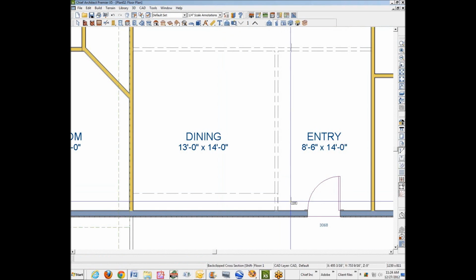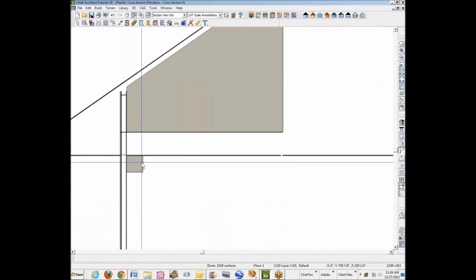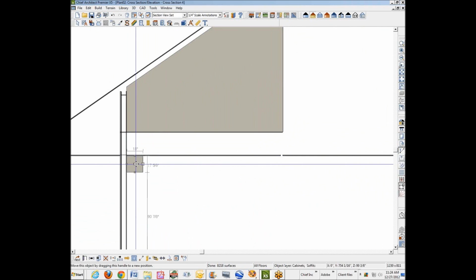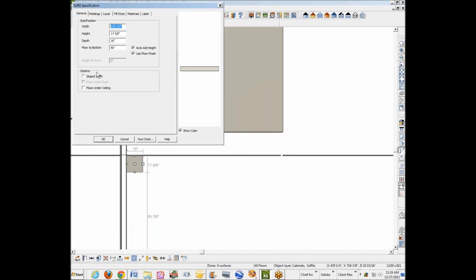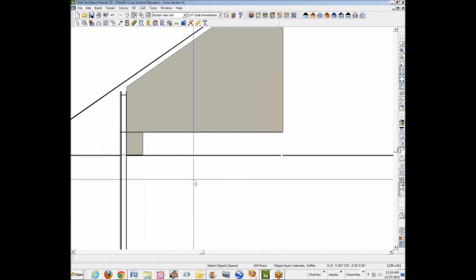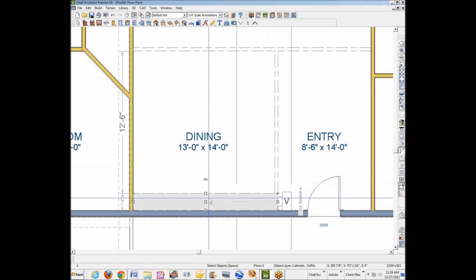Let's do a cross section. Yeah, okay. So they come in at the stated ceiling height for the first floor. That's fine. That's kind of expected. But I want the bottom here to be at 9 feet. So we'll set floor to bottom at 108. And the height, I've got it. We want the height in 24 inches, I think. Not very good at math, mate. Yeah, that looks about what I planned to do. So the flat will be at 9 feet, 2 feet tall. We'll just copy paste these around.